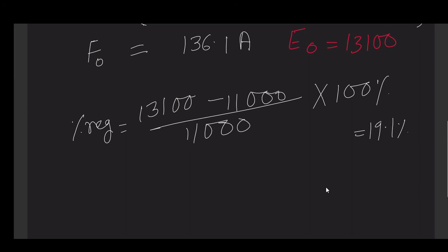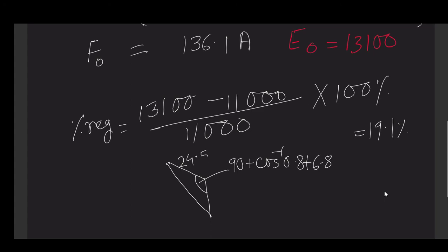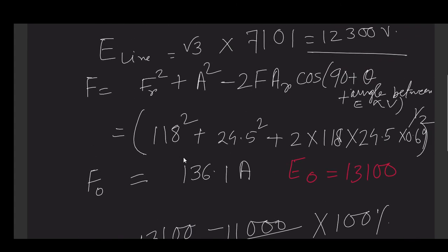Now the power angle will be how much? Power angle will be 90 plus cos inverse 0.8 plus, what was that angle, 6.8. This side was 24.5.